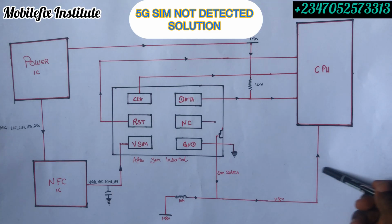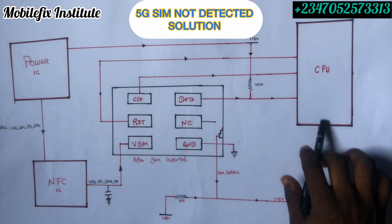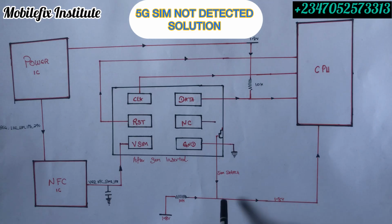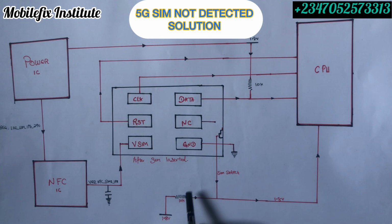So if this line is open, it's also important that after removing this resistor, on this side of the resistor, on diode reading, you test if you will get a value. You might get a value on this side, but you also have to test if you will get a value that comes from this CPU section. I'm giving you a deep explanation of how this circuit works. I want you to understand how it works. So also test, don't be in a rush, test this line. If this line gives you a value, that means it's not open from our power IC.